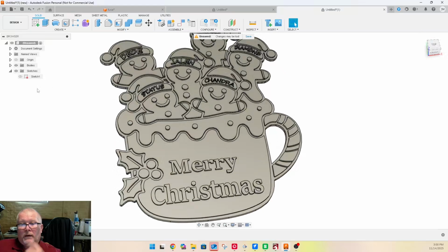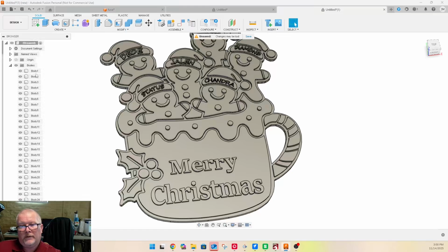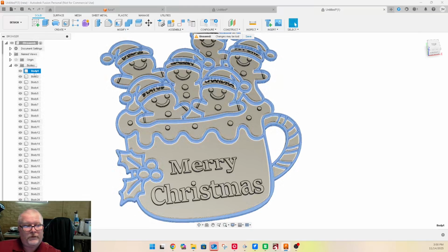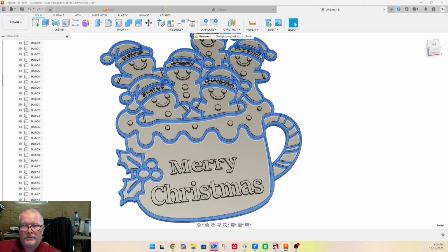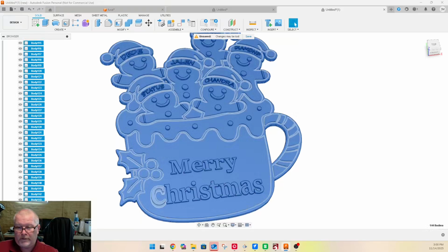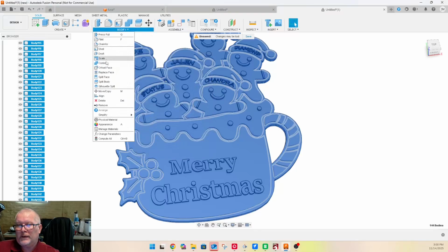Okay. Now, when we open our bodies, we're going to see, oh, we got a lot of bodies. I'm going to click the first body. I'm going to scroll all the way down. We're going to see it actually created 144 bodies. I'm going to hold my shift. I'm going to click the body number 144. We're going to go up to modify, and I'm going to combine.